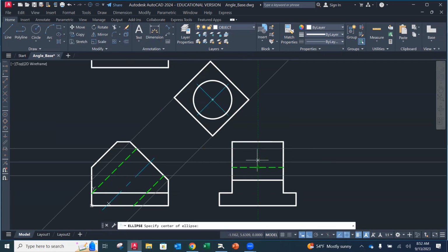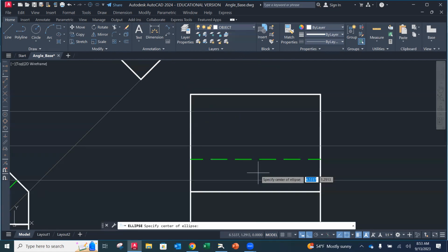The first thing we're going to do is find our center. Right now, you'll notice that this has a midpoint, or this has a midpoint, or this has a midpoint. You just want to activate that midpoint because that's the center. And we are just going to go down, down, down until it grabs the intersection of our construction line and the snap line that we have. Do you guys see that? Okay. There's my center.